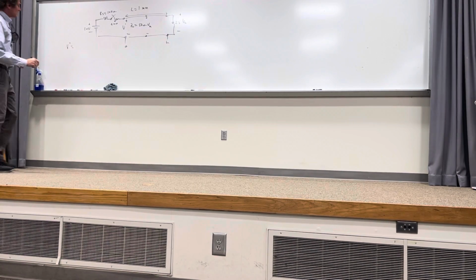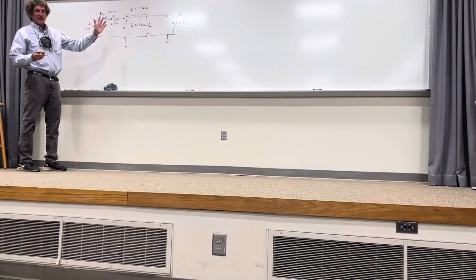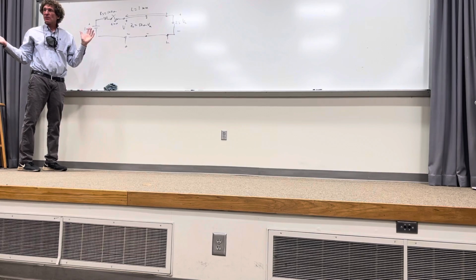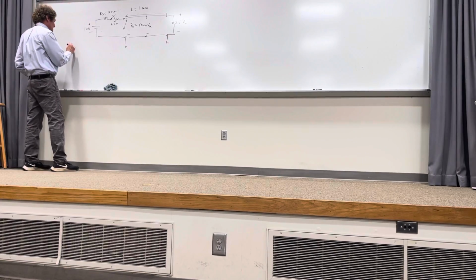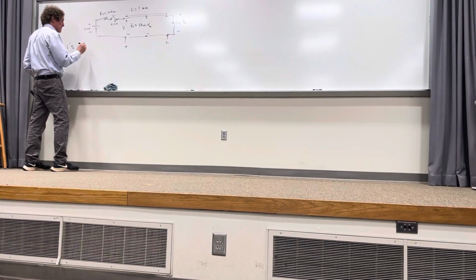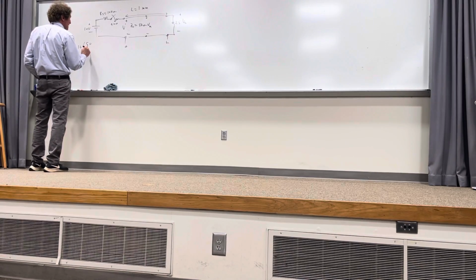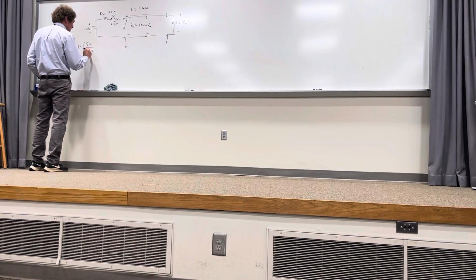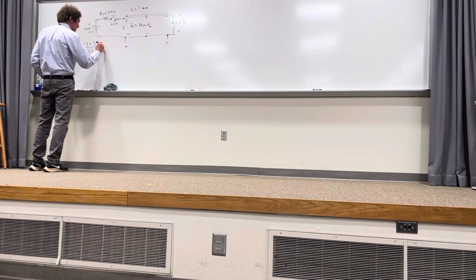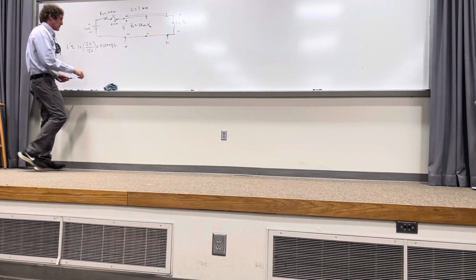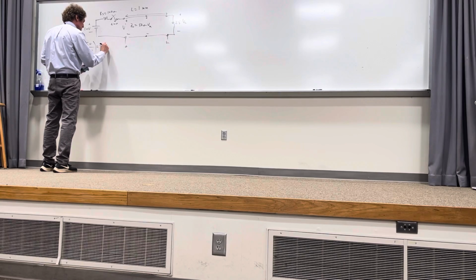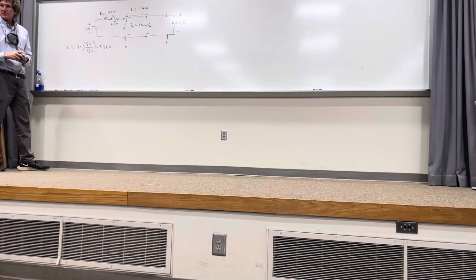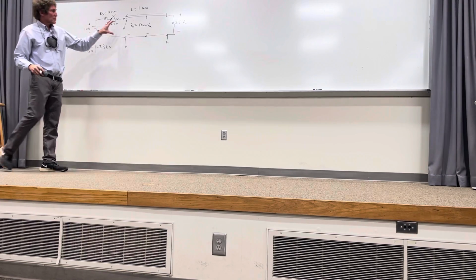Okay, so when you're doing this, what is the first thing we want to know? What V prime is? How do we get V prime? Anyone? Division. Yeah, we're going to use voltage division, and our load here will just be Z0, correct? So now we get V prime, and we say it's just 10 volts times 50 over 50 plus 100, or 150, right? So that's 1/3, or 3.33 volts. Y'all agree with this? 10 over 3 volts. That's the voltage that develops here and propagates.